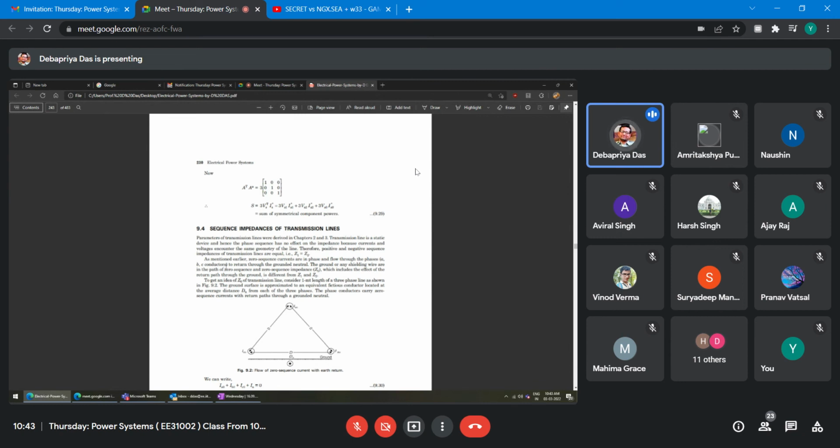So capital Y, and all small y were given, so capital Y can be immediately computed, right? No charging admittance, nothing was given. One should write all four equations, I1, I2, I3, I4, current injections, with capital Y. So I1 is Y11 V1 plus Y12 V2 plus Y13 V3 plus Y14 V4. Similarly, I2 is equal to Y21 V1 plus Y22 V2 and so on. Write all four equations.